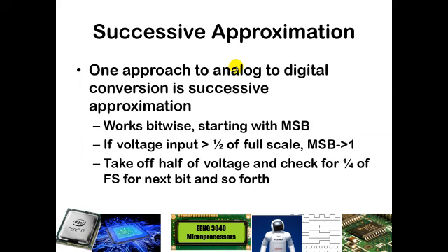The way these binary values come out is through what is known as successive approximation. With successive approximation, what we are using is a bitwise approach to quantifying the analog signal in a digital format. In this process, we examine whether or not we are above or below half of the full-scale voltage. Then we can look at the next bit by asking, is the remaining voltage above or below 1/4? And then we keep going all the way through until we get to our last bit, each bit representing half as much voltage as the previous bit.